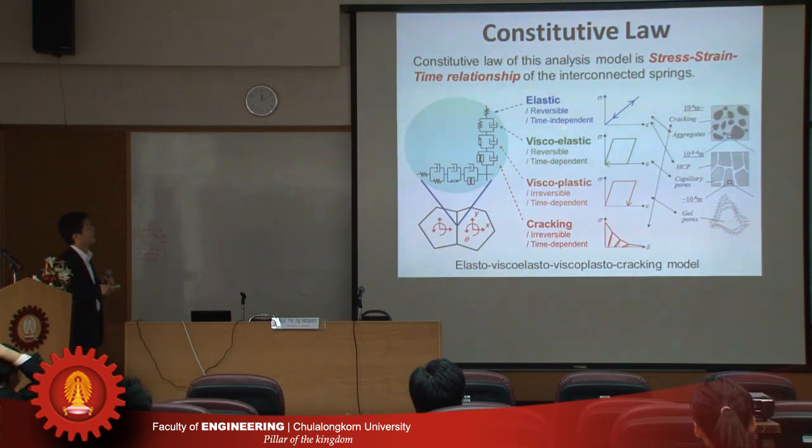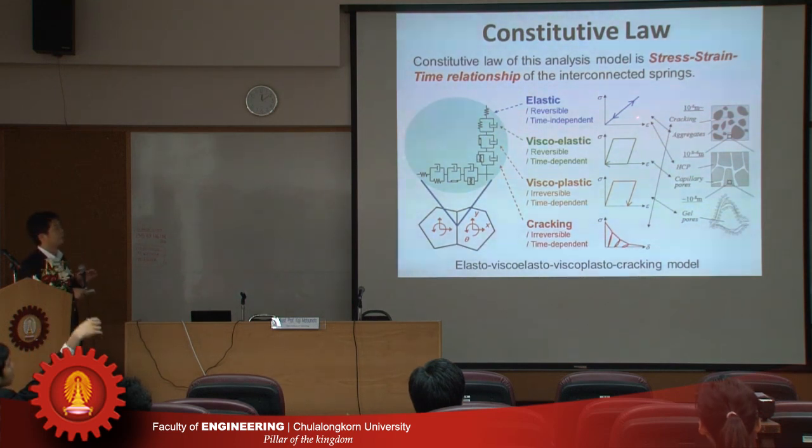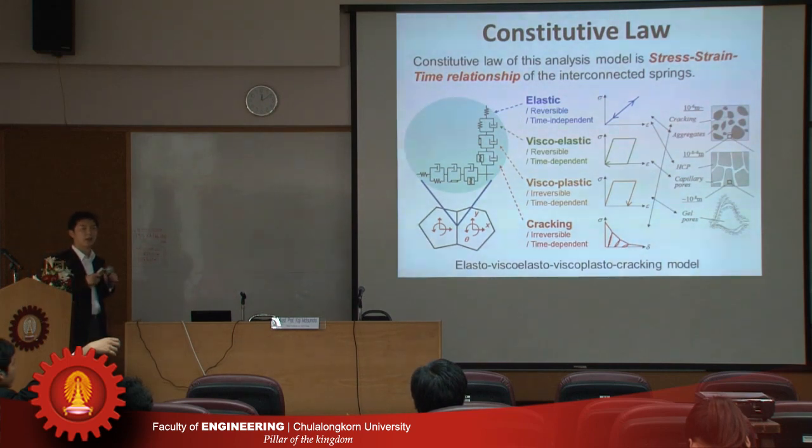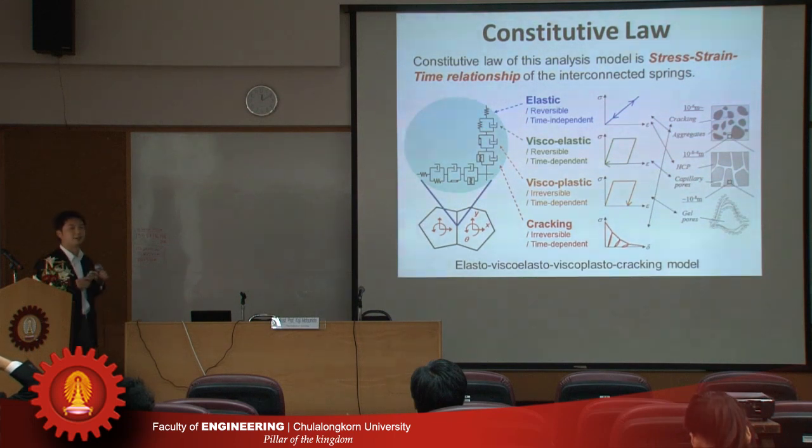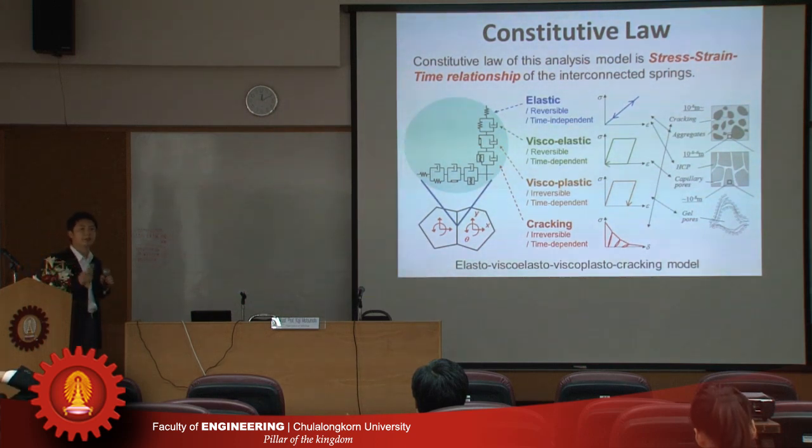For example, elastic strain represents the deformation of the aggregate and also the hardened cement paste. The viscoelastic strain is reversible strain since the elastic spring is connected here, but it is time dependent. The time dependency is represented by this dashpot element. And the third one, the viscoplastic element, is composed of a slider element and a dashpot.